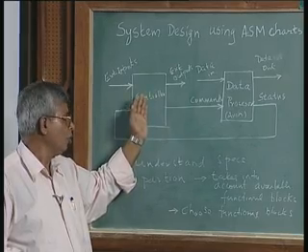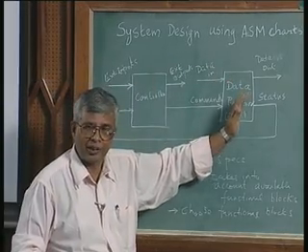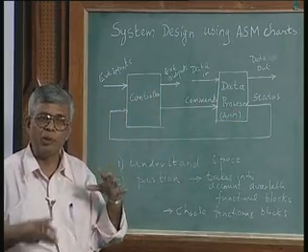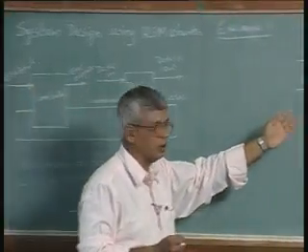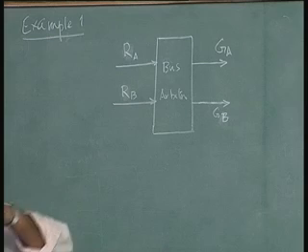I am sort of putting some of the controller function into the data processor by putting an extra counter there. Otherwise, my ASM chart is going to be extremely big. So that is the approach taken, and here it is also very difficult to partition it between bus controller and bus arbiter and anything else. Here it is only a simple circuit.